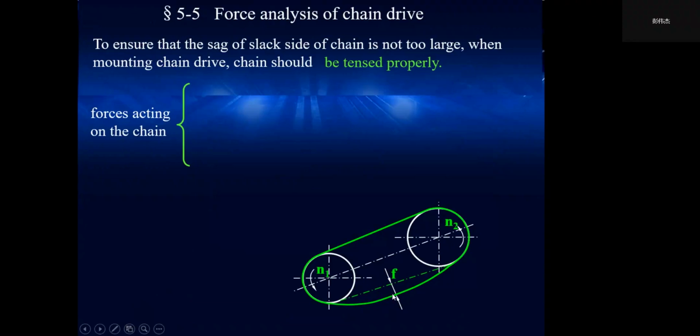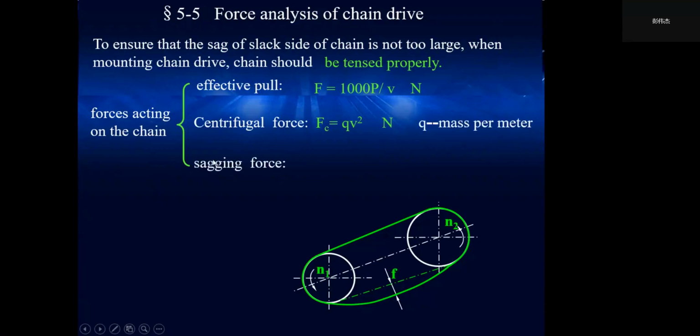When mounting a chain drive, the chain should be tensioned properly, and the forces acting on the chain include the effective pull force, or effective tension force, from the transmitted power, the centrifugal force, and the sagging force due to the weight of the chain.